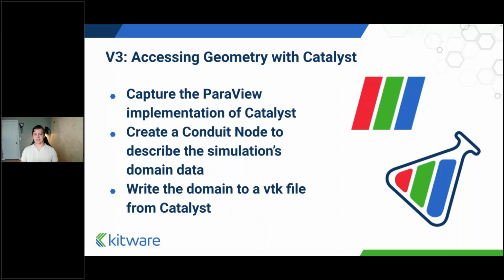This is a fantastic capability that can sound like a bear to compile your simulation against because of all of the crazy dependencies that ParaView requires for all of its massive functionality. Catalyst abstracts that away by simply dynamically loading that library at runtime. So you don't need to worry yourself, the simulation developer, with the actual deployment of ParaView.